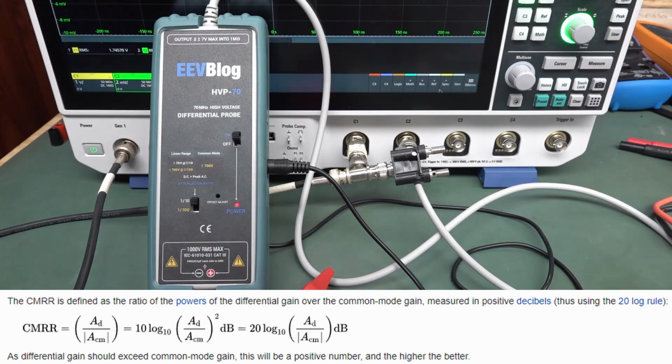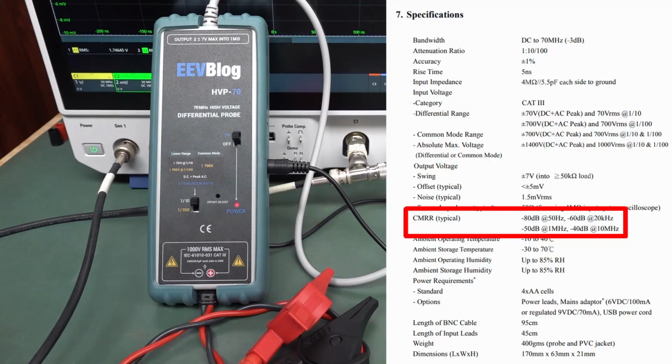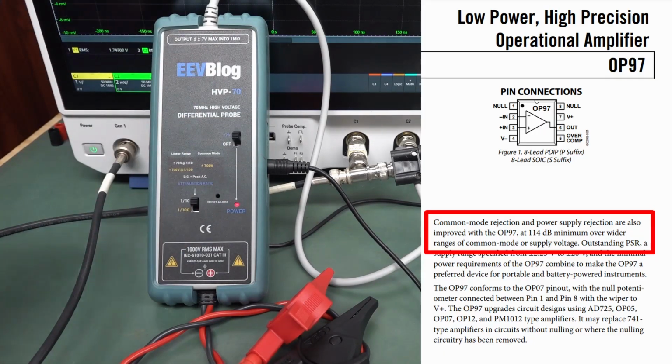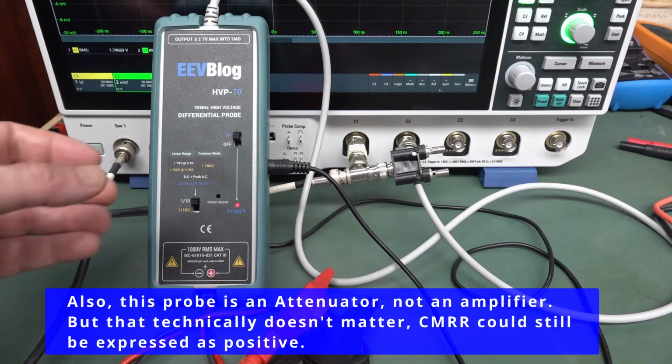So you just have to understand that when you're talking a negative number, in this particular case, minus 60 dB common mode rejection would be better than minus 40 dB. But if you specify it as a positive one, as you might get on, say, an op amp data sheet, here's an example, the higher the value, the better. So that positive or negative thing is just a little trap for young players, just be aware of that.